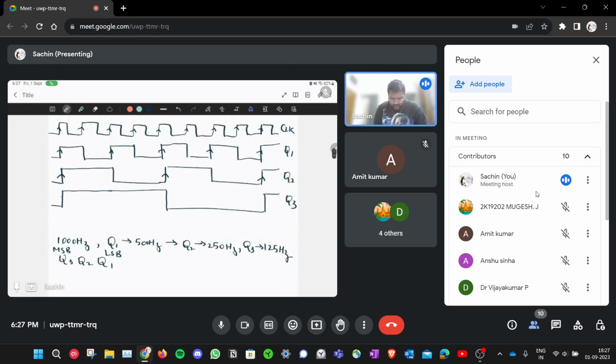If you see in the timing diagram, this is one clock cycle; it will go up, stay there for some time, go down, stay there for some time. Here the clock pulse is symmetric. So you consider the first clock pulse, you see that Q3 is 1, Q2 is 1, Q1 is also 1, so it's 111, that's the number 7, right?